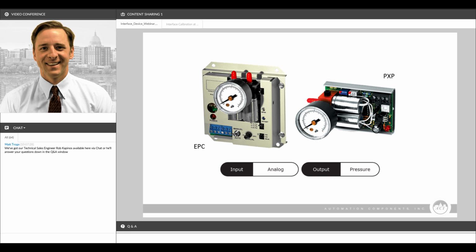Both of the ones that you see on the screen are the dual valve versions. These devices are what we typically recommend because they will hold the line pressure until a signal change is required. There are others in this series that are single valve, and so they'll have a constant bleed of air, and you can select the orifice size. There are different sizes, so the bleed of air will be faster or slower depending on that size.